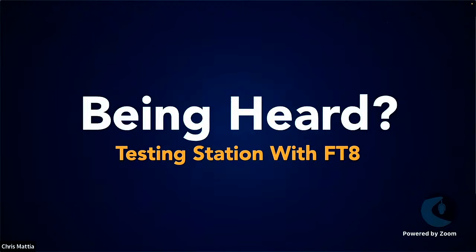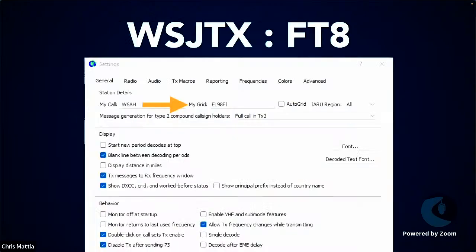Or you can just ask yourself, hey, am I being heard? And a great way to check that is by testing your station by using FT8. Now, with FT8, when you first launch it, you'll want to go into the settings section of your FT8 setup, and you're going to want to change your grid square. It's right there on the general tab. Pretty much the first line that you come to, you just go ahead and enter in that new grid square that you're going to be operating from.